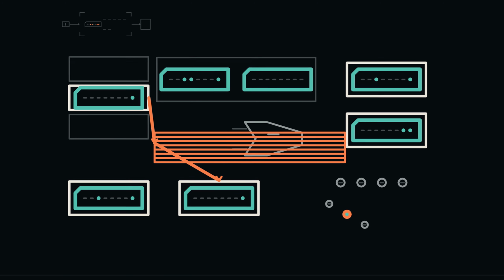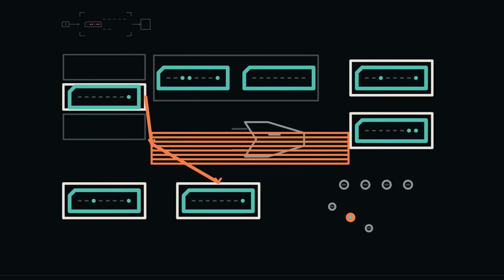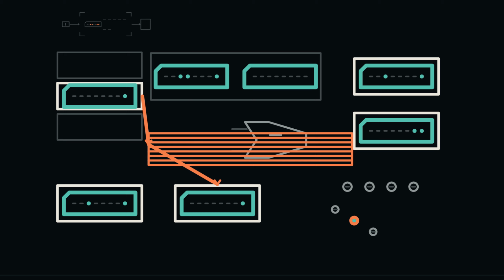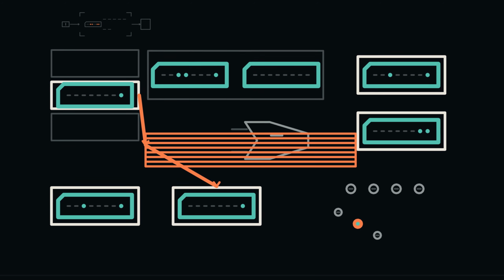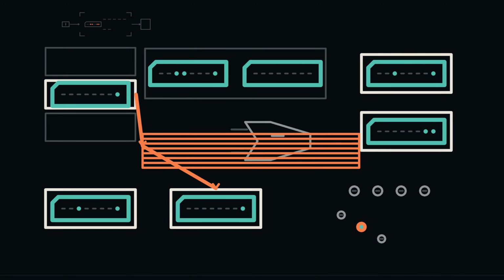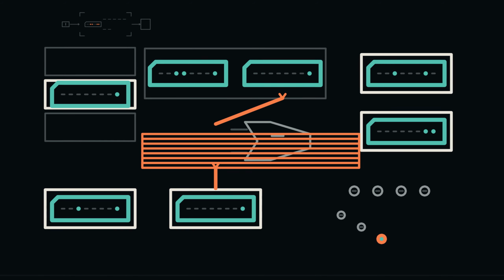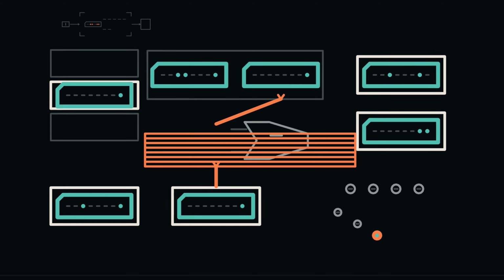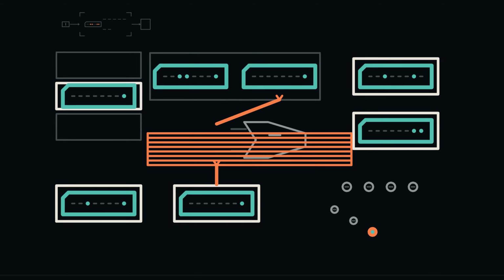No arithmetic has occurred. Before the final latch edge, predict PC, instruction register 0, instruction register 1, and R0. PC is 21. Instruction register 0 remains 31. Instruction register 1 still holds its old value. R0 remains 3. Keeping these old values visible makes the upcoming simultaneous changes accountable. At fetch 1 latch decode, instruction register 1 captures hexadecimal 01 from MDR and PC advances from 21 to 22. The 2 instruction registers now preserve 31 and 01 together.